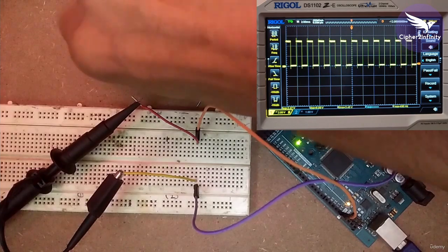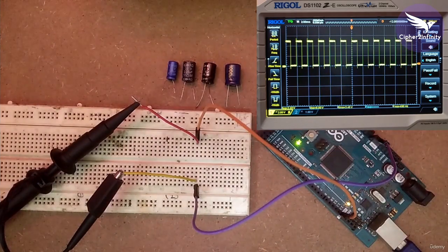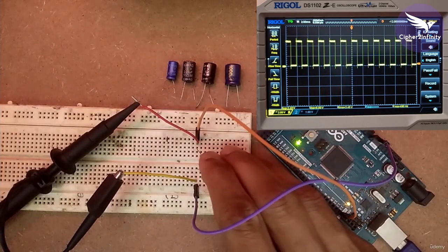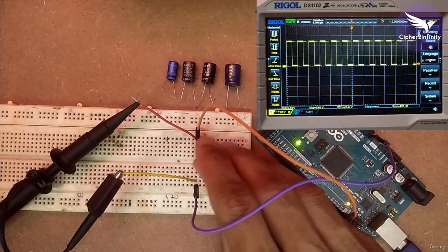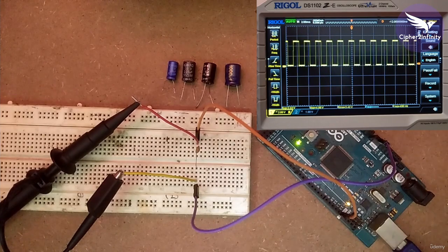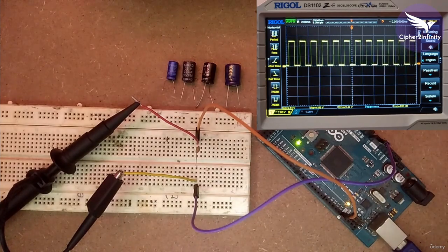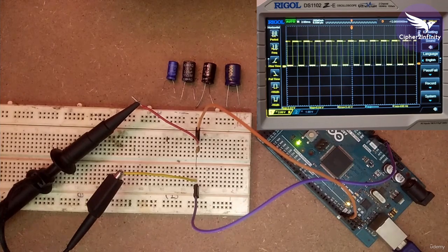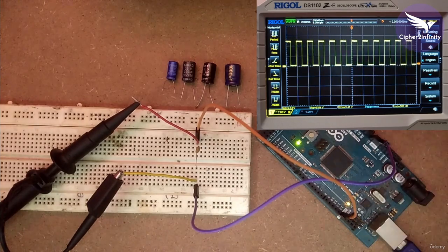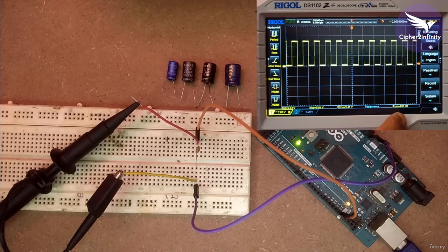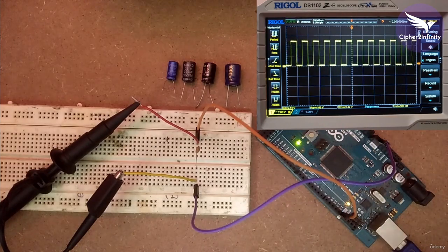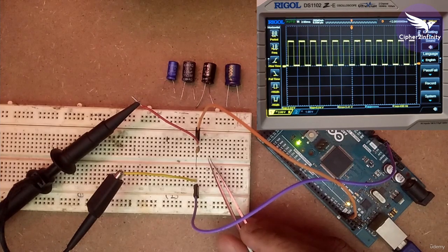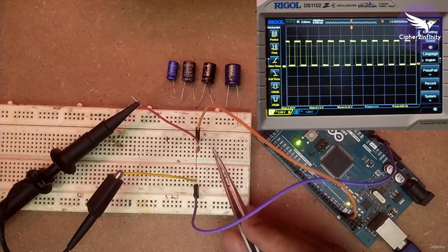First of all, let me connect this 100 nanofarad capacitor between these two pins, the signal pin and the ground pin, and you can observe this signal on the DSO. You can see on the DSO the signal is not filtered, and we are still getting a frequency of 500 Hz. You can observe this frequency here, 500 Hz. So it means that this particular capacitor is providing a very high impedance to this signal.